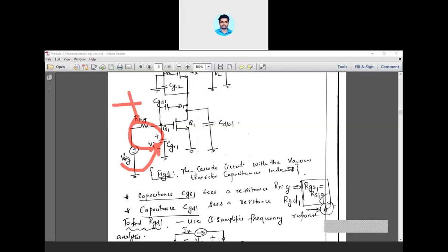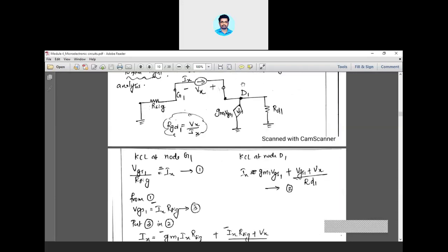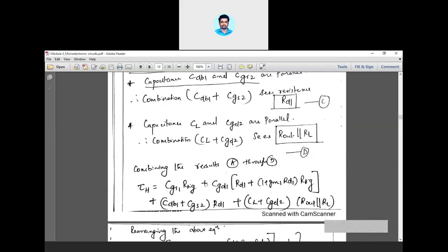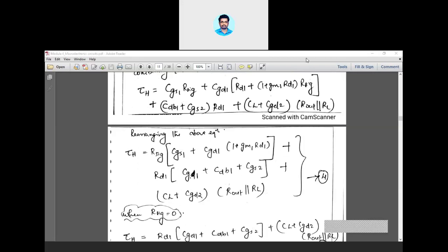Now here as a special case, we are analyzing the frequency response without RC. So in this resultant equation I'll be putting RC as 0. Wherever you find RC, take it as 0. So this term will vanish, isn't it? This term will go. So only these two terms will stay back. The first term will be cancelled because of setting RC equal to 0.